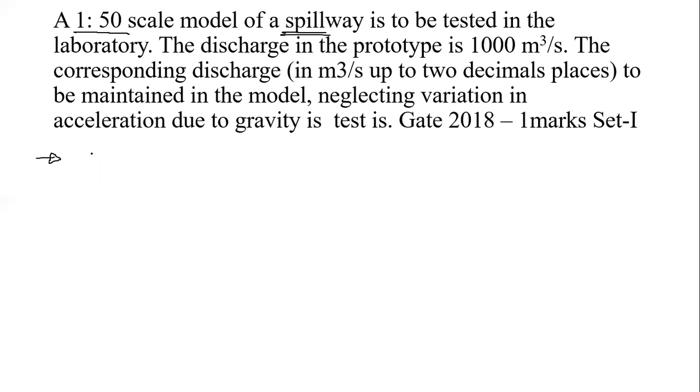As with the previous one, only the question is there, but I would have to go for the solution. The given data includes the length scale ratio LR = LM/LP = 1/50. In some books you will find the ratio the opposite way, LP by LM, prototype to model, but you will get the same answers. The discharge ratio will also be inverted, and likewise we will get the answers, but I am following the standard methodology of model to prototype.